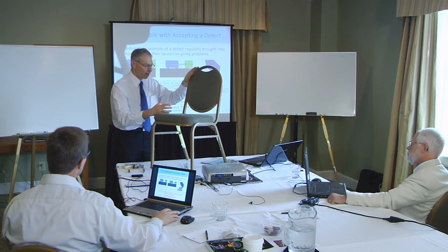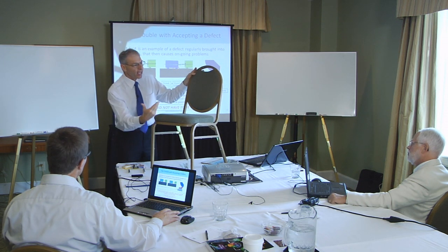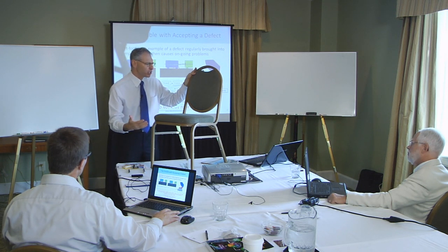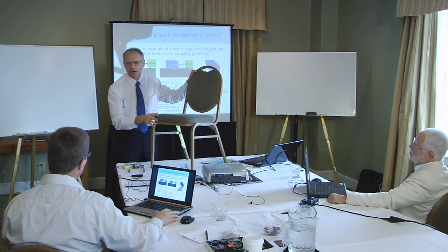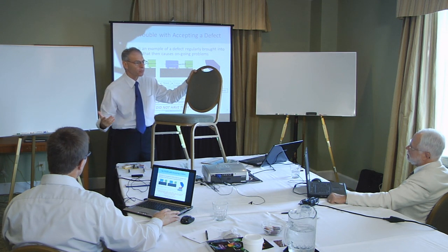They're going to be distorted, and that's a brand new machine. Internally, my parts are already under high stress and the machine hasn't even been used yet. And if I use the machine when the parts are under high stress and they're banana shaped or squashed together very hard, they're not going to last very long. Press the button, the machine will go. It'll just fail in a matter of months when it should have been many, many years of trouble-free operation.